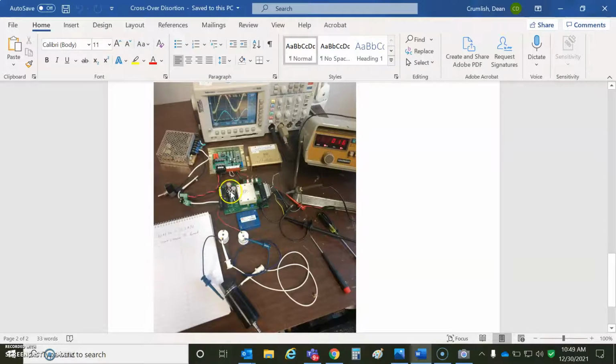Local bulk capacitors, probably 470 microfarads for every 5 amps you deliver. So this is a little excessive, but this board is for the 1020 also. So it's not a bad idea. Also could take 75 volts, so one development board. A couple of switches for enable. The program header is here if you want to protect the motor from excessive current.